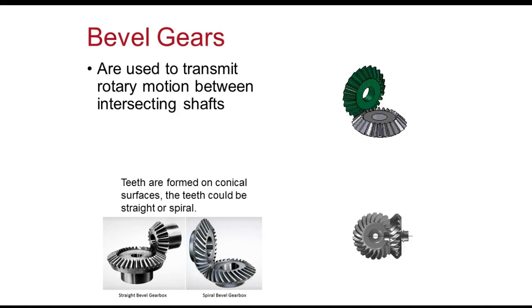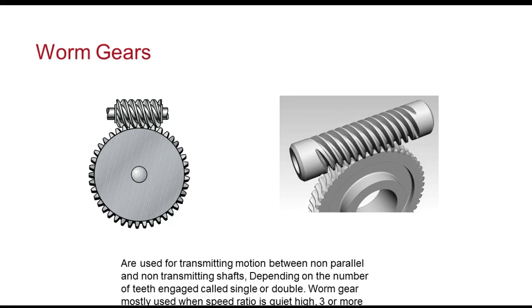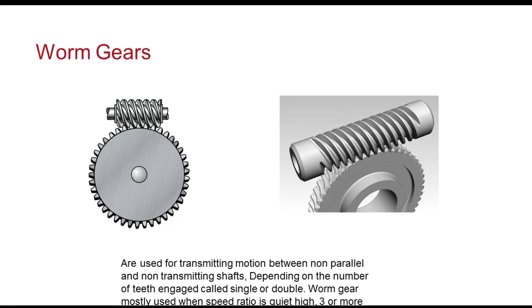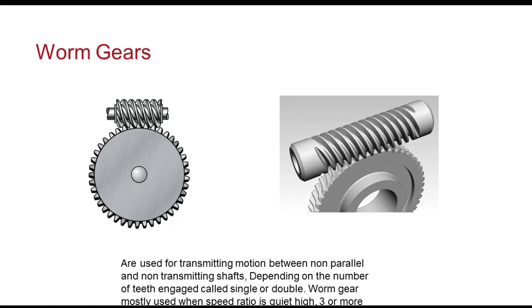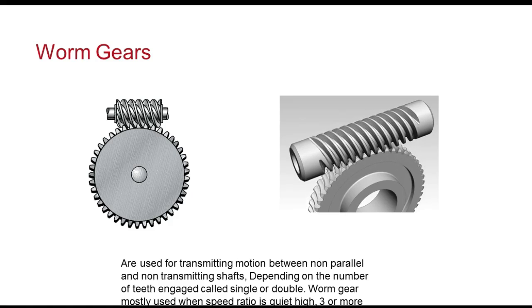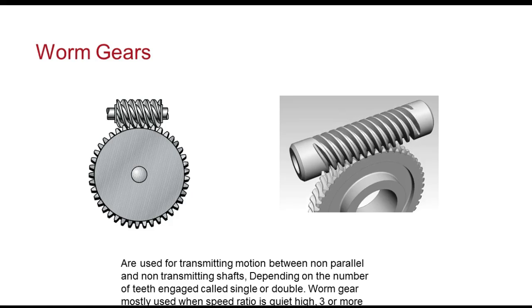So if you look at the shaft of the stepping motor, it's got the worm on it, and then the thing that spins around there, and it's throated too, if I think right. The gear is throated. So if it's throated, that means the worm can get in there. The teeth make more contact. You got more teeth in contact. So this is a worm gear. Now, of course, the advantage of worm gear is you get an extremely high gear ratio.